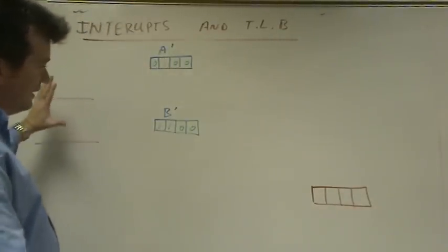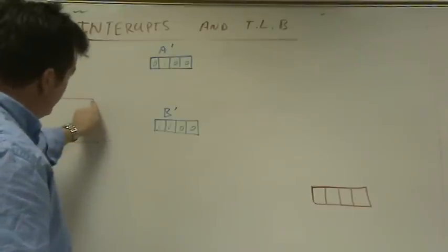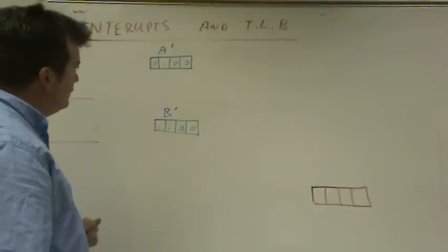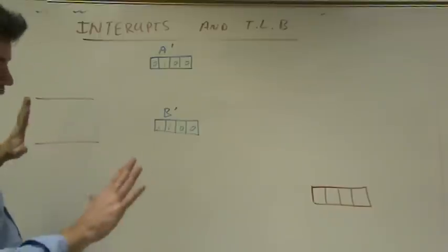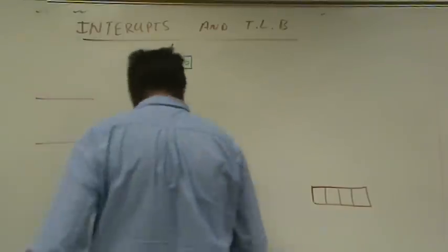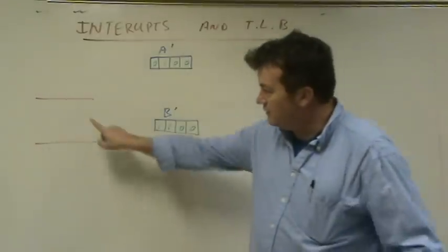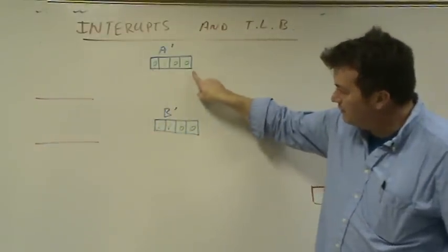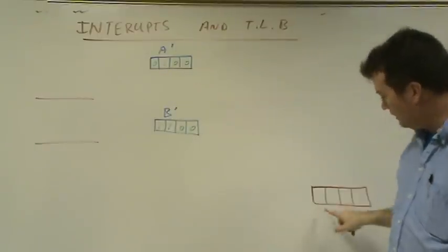But here's our goal. We want to come up with a piece of hardware that if this line is turned on, and we'll actually say we promise that at most only one of these lines will be turned on. They can't both be on. So the question now is, if this line is turned on, we want this entire register, which I randomly said 0, 1, 0, 0, to show up here.